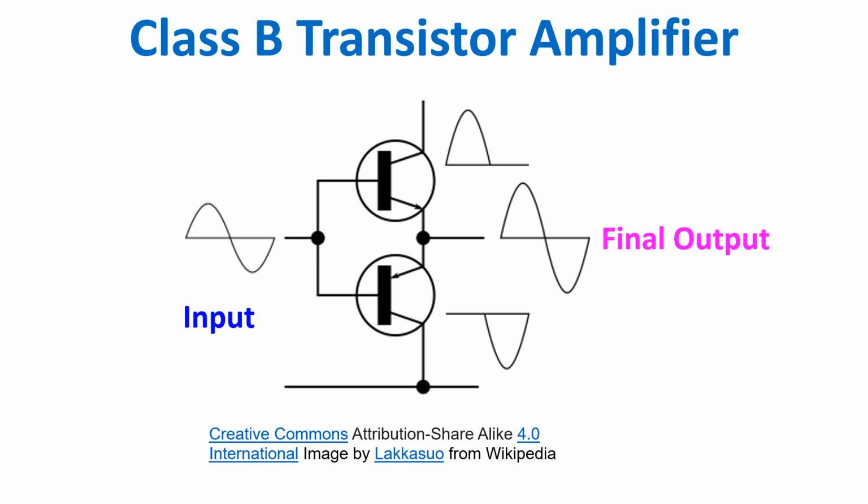Each transistor conducts for one half of the signal cycle and the outputs are combined so that the load current is continuous. Class B amplifiers have a higher efficiency at around 60% as current wastage is lower. They are favored in battery operated devices like transistor radios. There is some distortion at the crossover point as one device has to take over supplying power exactly as the other finishes. This is known as crossover distortion.